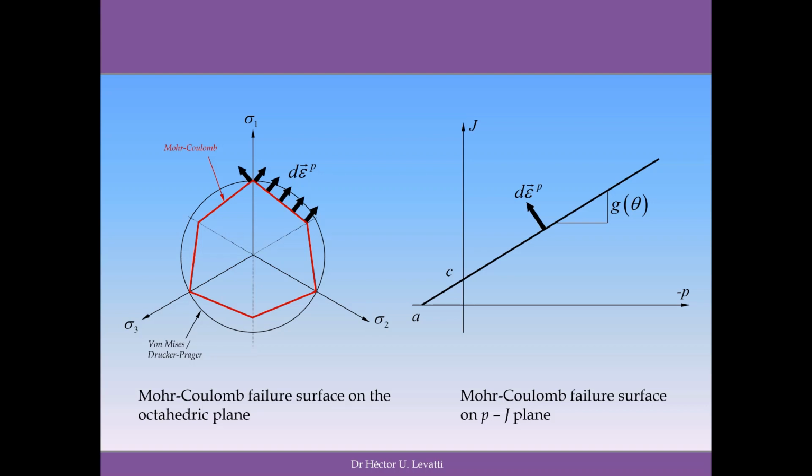But the important message in this presentation is that all these concepts are related and all of them are useful to do analysis in geotechnical engineering and in structural engineering in general. So the concept of the stress tensor, the concept of Mohr-Coulomb failure criteria, the concept of the Mohr circle, and the effective stress, don't forget the effective stress, which is the most important, they are all linked and they are all useful to run very complex and very useful geotechnical analysis.